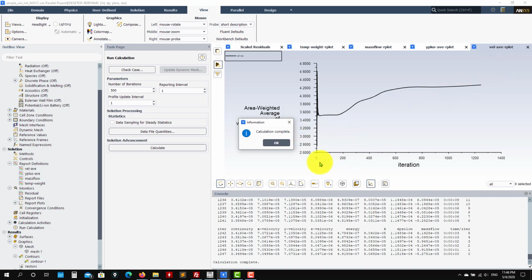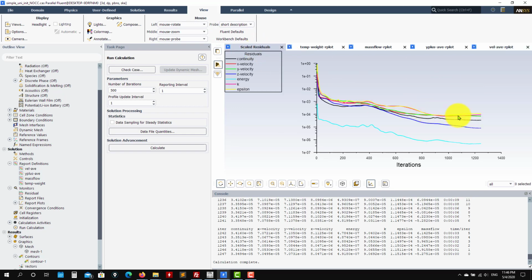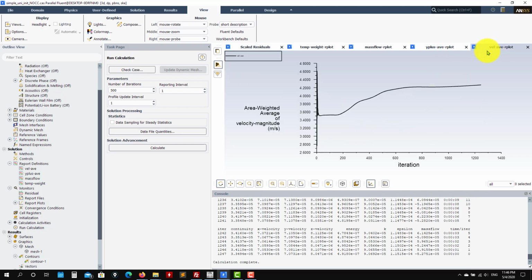Okay, we're back. We ran an additional 500 iterations, and see the behavior here. It had previously converged about here, so it wasn't fully flat. Then we let it run and see that it's getting flat, though it might be oscillating a little bit. This is part of CFD: not only looking at one quantity. This one converges very well in a monotonic way, but then you monitor some other quantities and you see different behaviors. So let's say that we can stop here. Also take into account that, as you're going to see, we're going to have a vortex, so probably the oscillations also come from the outlets.